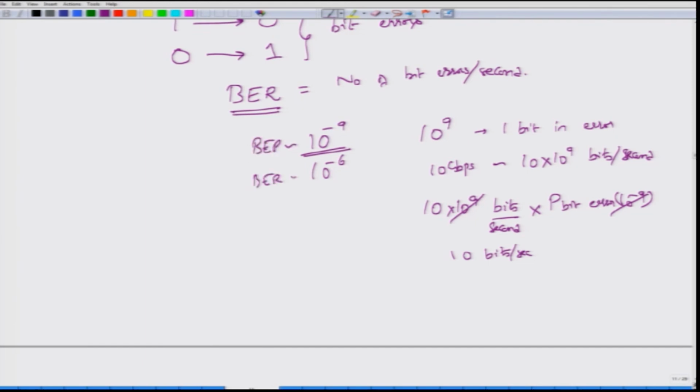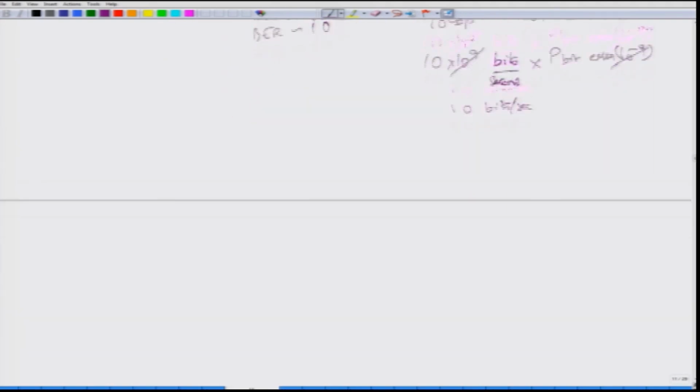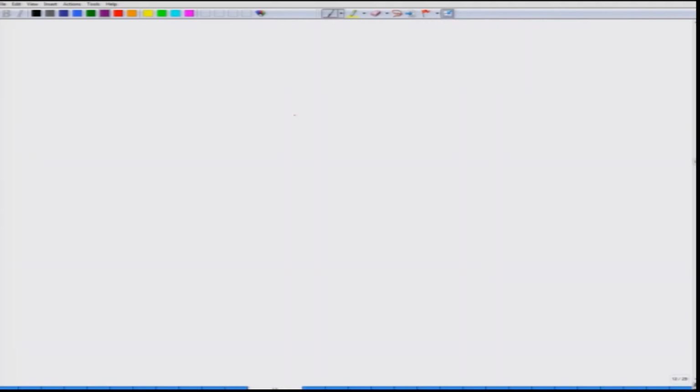But the colloquial use is that you use the same value for bit error rate; you do not really talk about bit error probability, because you kind of normalize it with the transmission rate or the data rate. So, this is BER. In optical communication systems, you also find another performance measure which is called the Q factor.